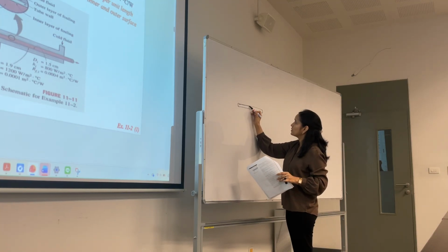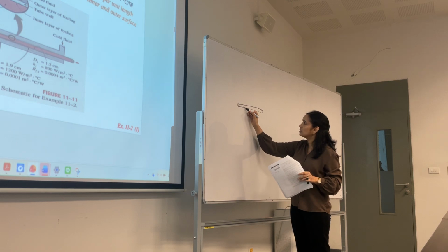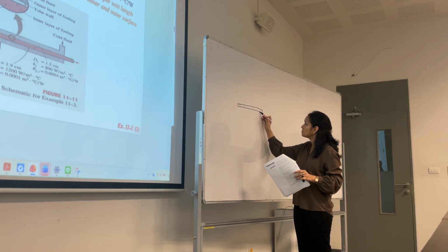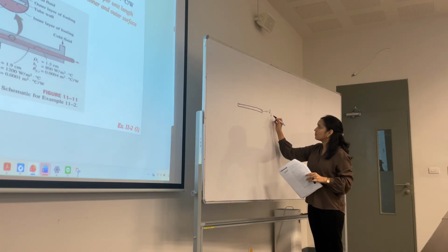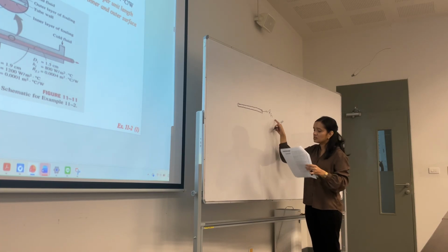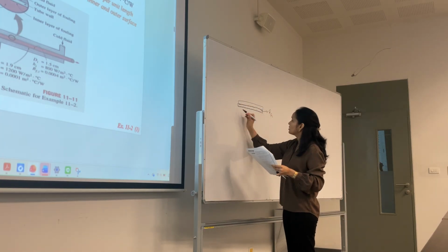Corrosion or precipitation, which is causing resistance. So this is called fouling factor inside. This is a type of resistance. RF, fouling factor resistance inside. I is for inside. Then there is a tube outside. It's a double pipe, right?